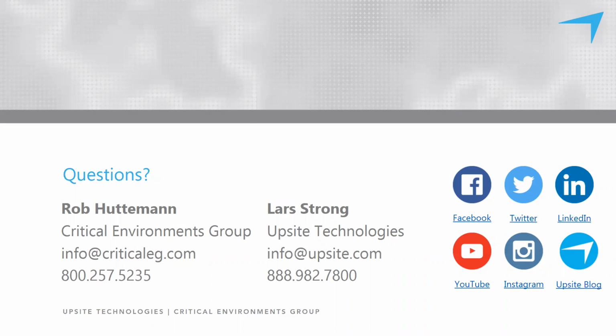your heat related issues, or what you're perceiving, may not be things that you're actually causing, right? It could be your neighbor, it could be large network switches blowing hot air directly into your, call it, cold aisle. So there are a number of things that can be done to remediate this, but it all has to be done in the context of improving your situation without making someone else's worse, whether it be a client in that room or the actual colo itself. So we try to make sure that there's always a clear path for the return air to get back to the air conditioning units. That's key. We don't want to ever block that from happening.